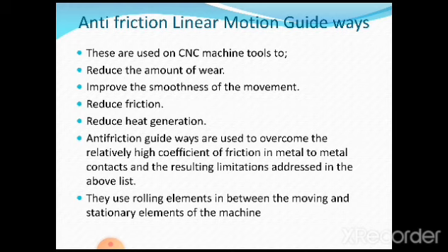The recirculating linear roller bearings are used for movement along a flat plane. The basic requirement is like this: in place of balls, we use rollers. That's all. They are used for movement along a flat plane, meaning along the linear direction. Their main characteristic feature is that there is a continuous roller circulation, which allows unlimited linear movement.